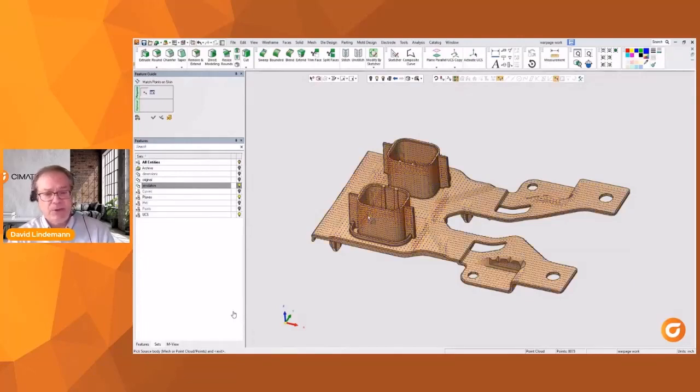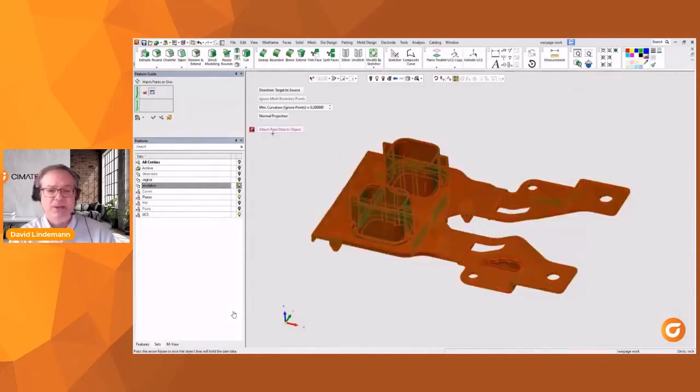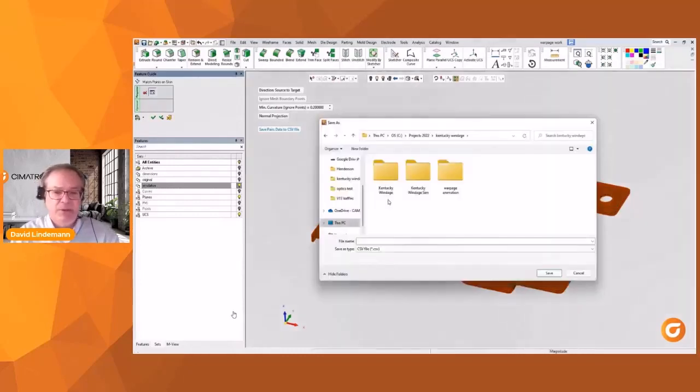All right, so let's take those points now, and we're going to work with the STL. We're basically going to snap them down to the STL surfaces and compare the distances. And the way I like to do it is to keep a separate file. So this is a CSV file, or comma delineated kind of file. And I do that because I may have other iterations of this. I may go back to the simulation, tweak the water, run it again. Now I want to compare the two. Well, I've got the simulation with the points set as it was initially, say out of the box, or how I've maybe tweaked the process, or how I've tweaked the design. So I can keep those different versions available for me at any time.